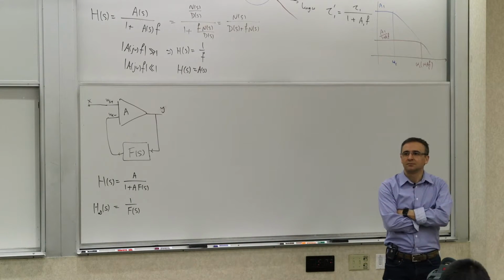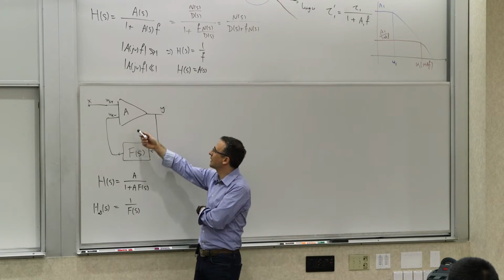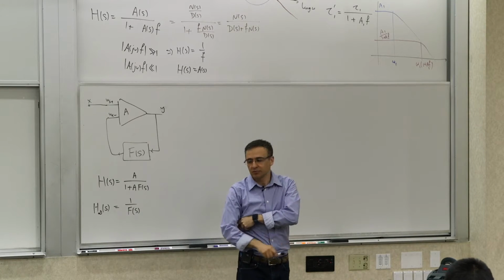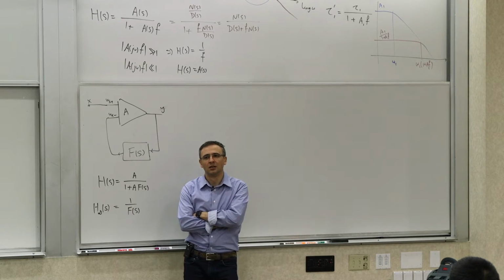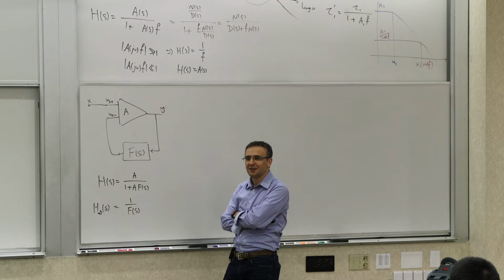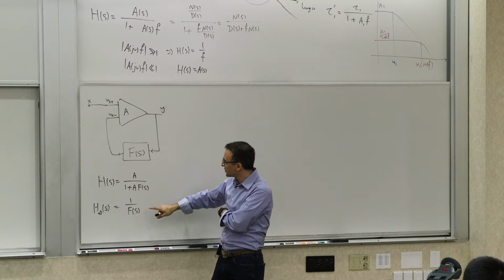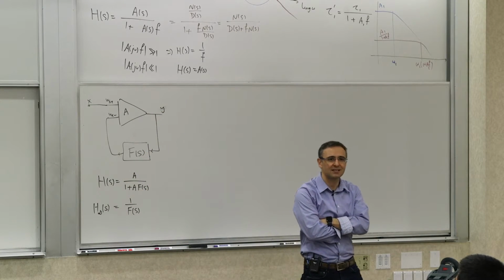What does that mean? What did feedback do? This is a lot of feedback, a lot of high quality gain applied, which you can have depending on what frequency your dynamics is. If this is relatively low relative to the dynamics of this guy, something close to this can be achieved very easily. What is this new transfer function? What has happened to the poles and zeros in this case? They have switched, right? They have swapped. Because now the transfer function of the closed loop system is 1 over the transfer function of this thing. So this is actually the inverse system.